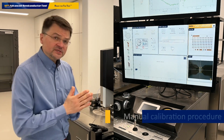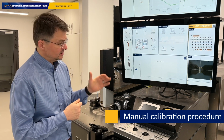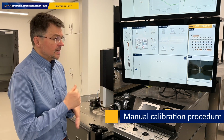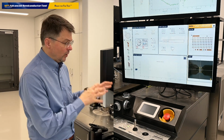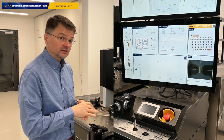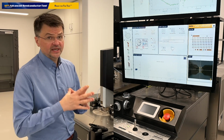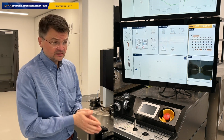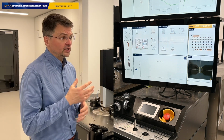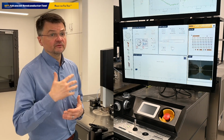So, let me demonstrate how you can manually trigger the calibration process and move from one standard to another standard and check also the consistency of the measurement results acquired by the system on a particular calibration standard. Consistency of the measurement data is important because it is the key to a successful calibration procedure. So if the data are not consistent, if the data are not repeatable, or if data are affected by some mistake, then your calibration will fail.